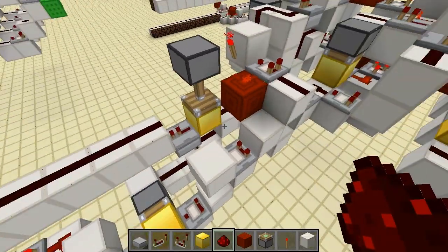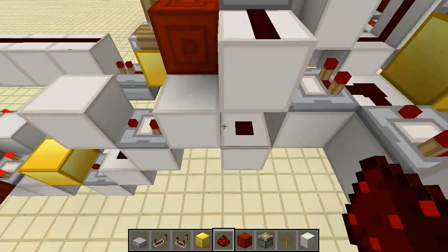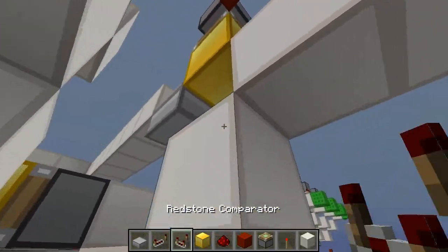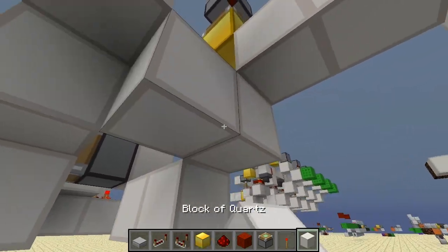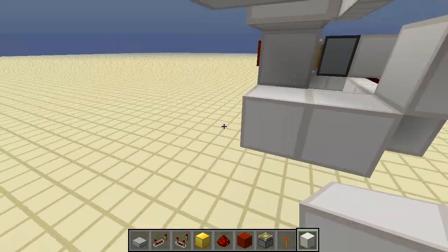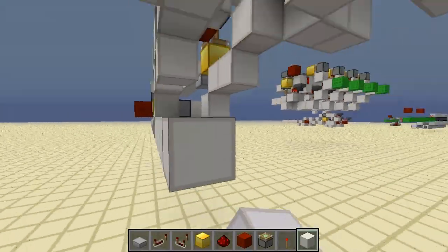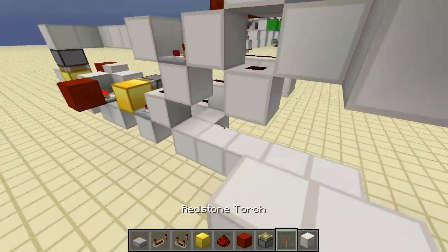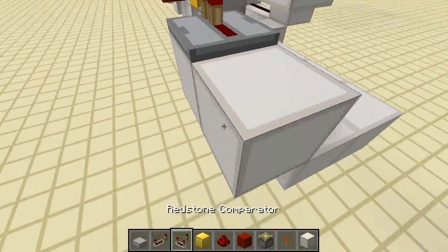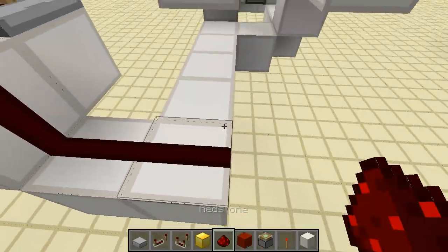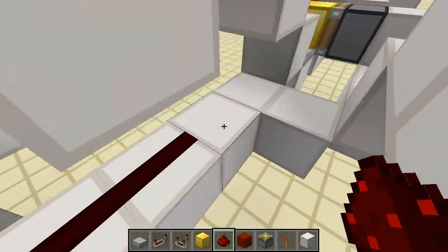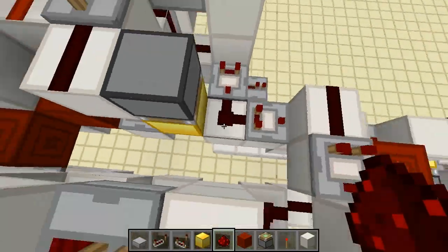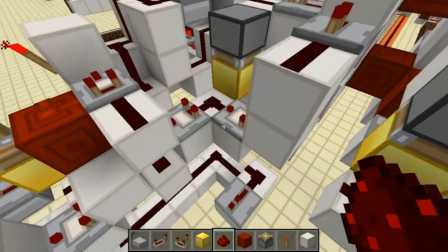It's actually impossible, of course, just in case you didn't catch the sarcasm there, which I'm sure you all did. So we need to take this carry out signal, and the easiest way to do that is just to come down here, back to here, I believe, yes, up and out, with a repeater here. So that means that the carry takes 1 tick, which is very nice. It's almost instant carry, but the wiring isn't long enough in this orientation, unfortunately, to manage instant carry.